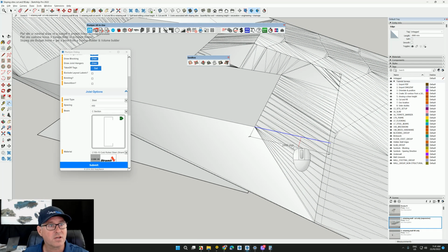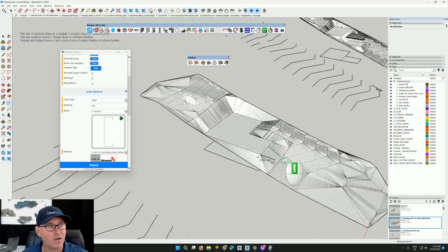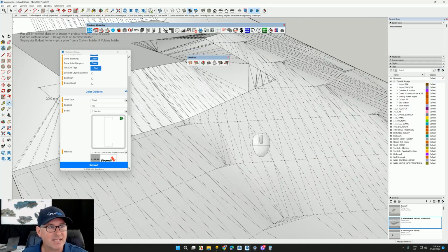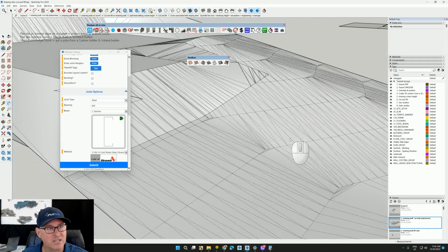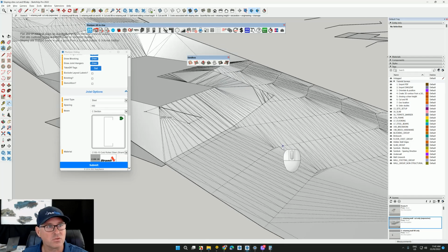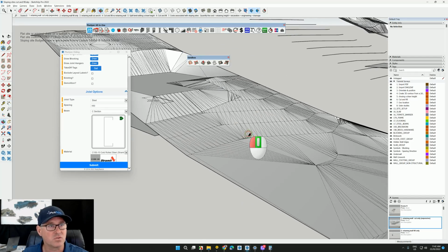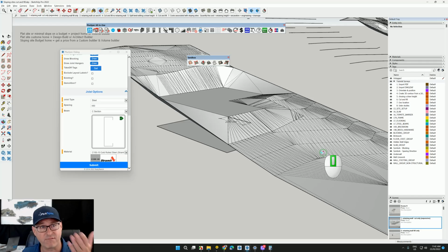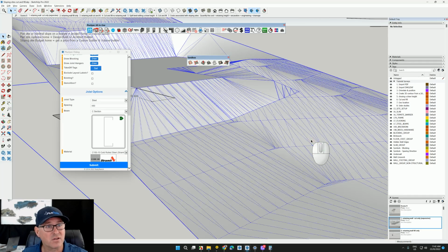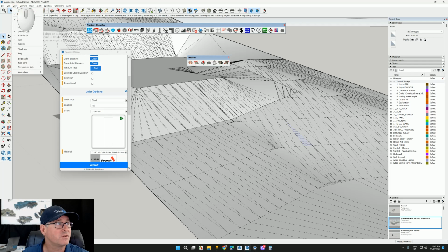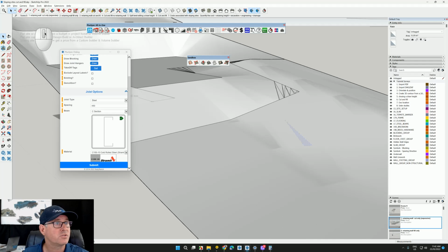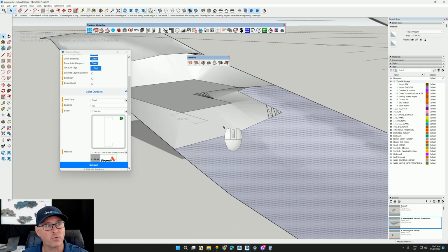Now, guys, you'll also notice I'm looking at the geometry behind the scenes. SketchUp doesn't actually make curved faces. It creates triangles to ensure that we can get this to all mesh, and I have a face there. If I got inside of here and clicked in, you'll notice that I have individual faces now because I have hidden geometry turned on. To turn that off, it's View, Hidden Geometry, and now when I select it, I have the full face selected.